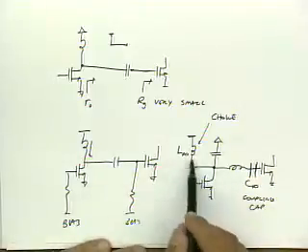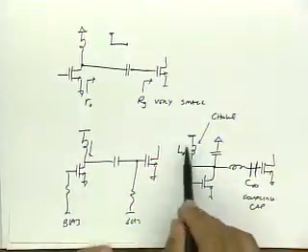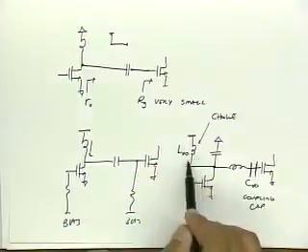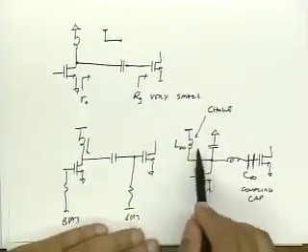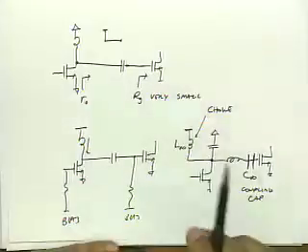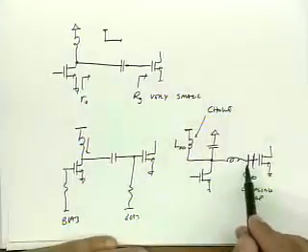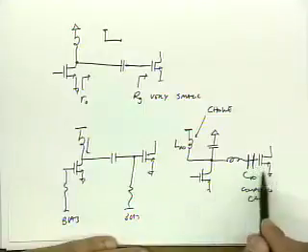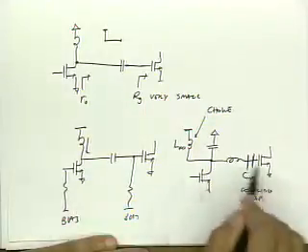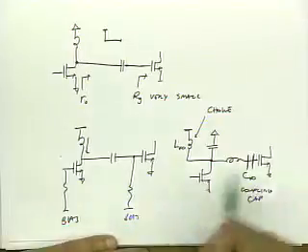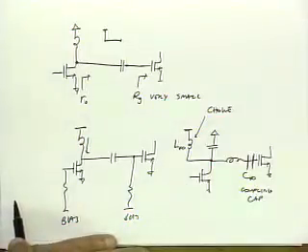And in practice, basically any large inductor acts like a choke. It doesn't upset the AC operating point because at RF frequencies it looks like a high impedance, and so it kind of disappears. Same with a capacitor. If I put a very large capacitor in series, at high frequency it looks like a short, so it doesn't upset anything, but it does prevent the DC operating point of this stage from interfering with the DC operating point of this stage.